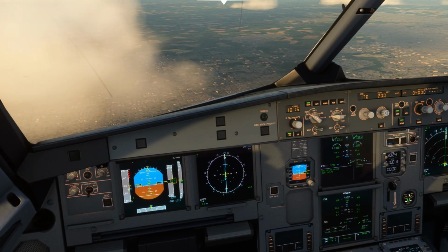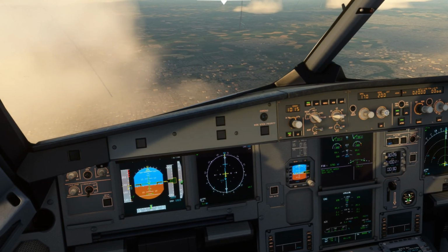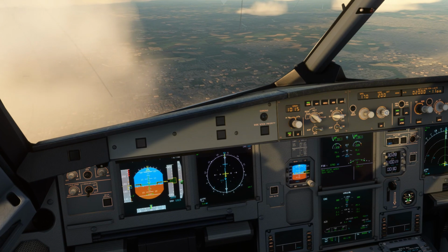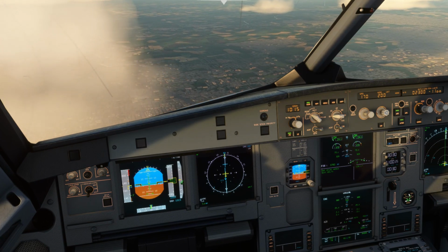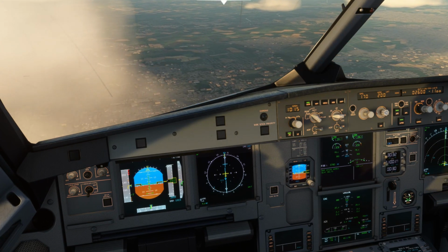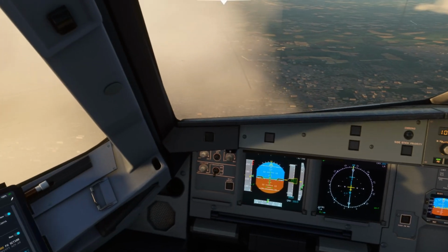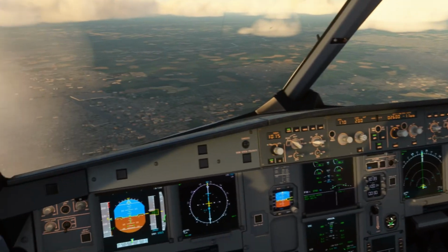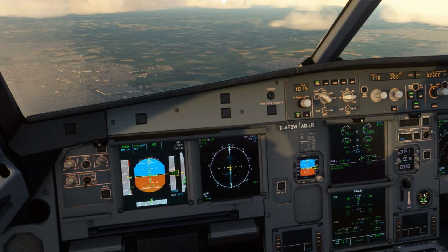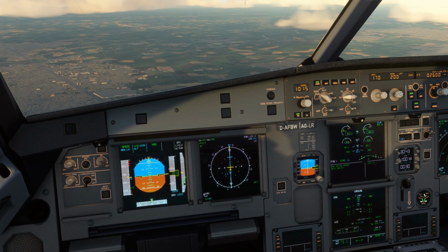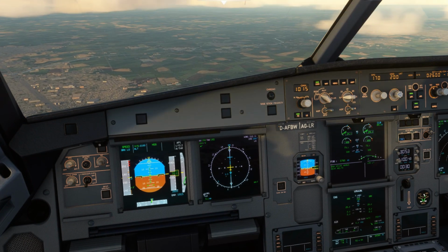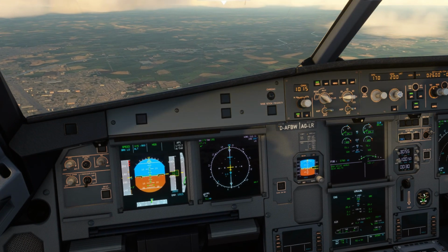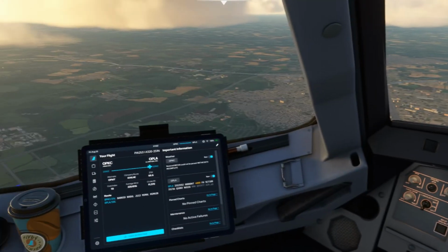Descending down to 2600 feet. Minimum safety altitude is 2600 feet. It caters for all obstructions around 25 nautical miles of this VOR. 4.5 nautical miles. Descending down to 2600 feet, 5 nautical miles out from Lahore VOR.